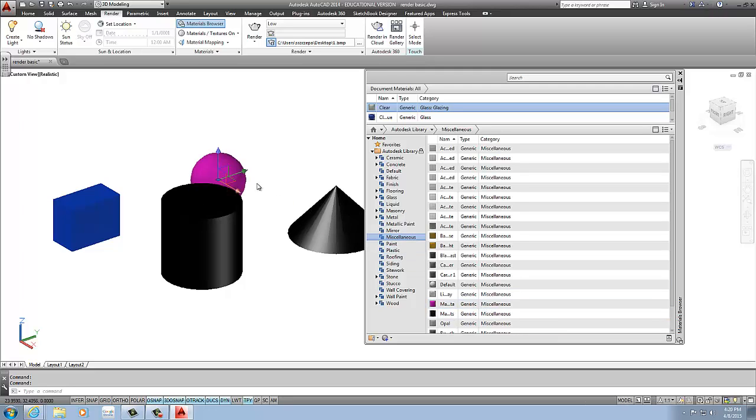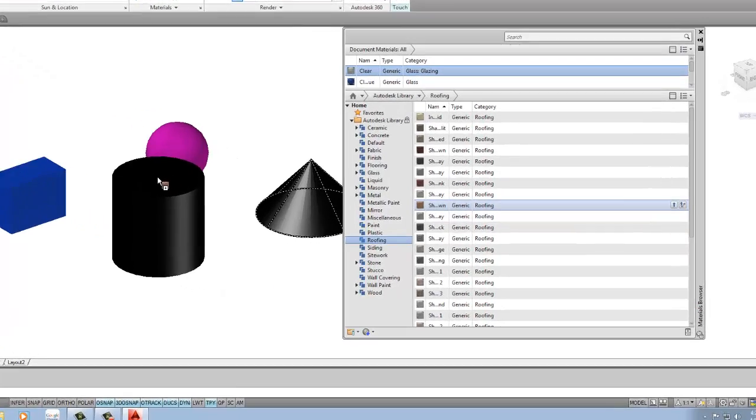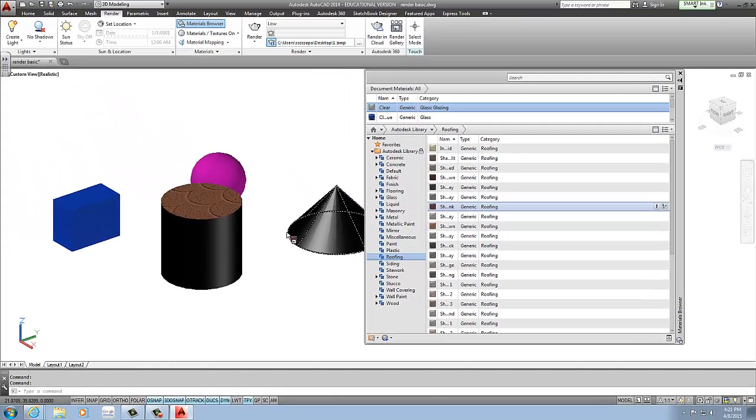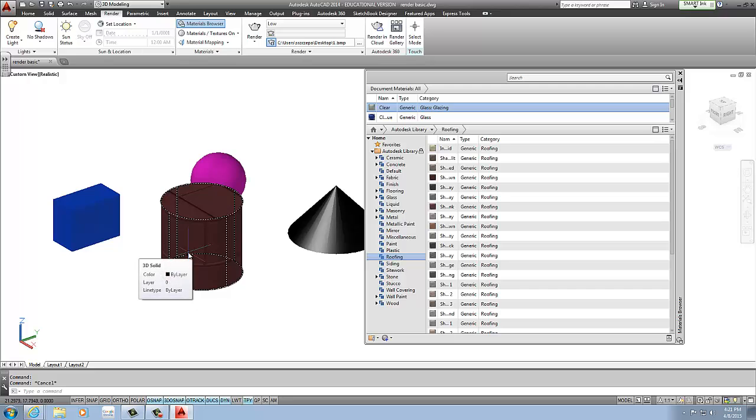Now you can do that for all different materials and all different parts. The other benefit is you can also, by holding control, do a single surface. So instead of doing the whole entire object, you can do a surface by holding control and dragging the material onto that surface. But then again, if you drag it on the part again, it will replace it. So keep that in mind. If you're going to do one surface, make sure all the other surfaces are done the same exact way.